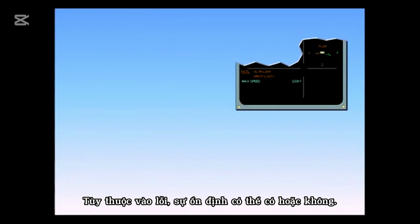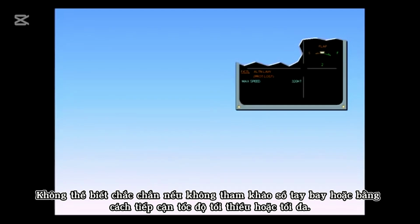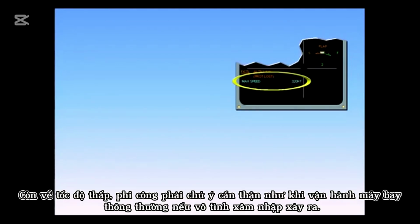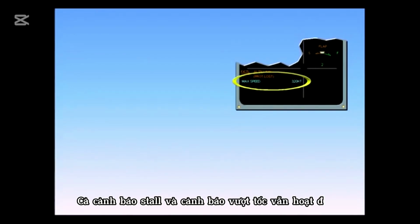Depending on the failure, stabilities may or may not exist. There is no way of knowing without reference to the flight manual or by approaching the minimum or maximum speed. Airbus has restricted speed to 320 knots to prevent an incursion into the high-speed regime. As for low speed, the pilots must exercise the same care and attention they would when operating a conventional airplane. Should inadvertent incursion occur, both stall and overspeed warnings are still operative.